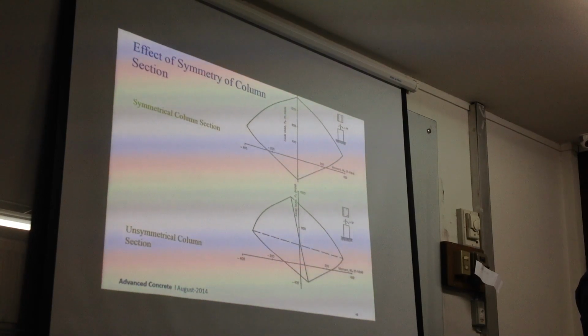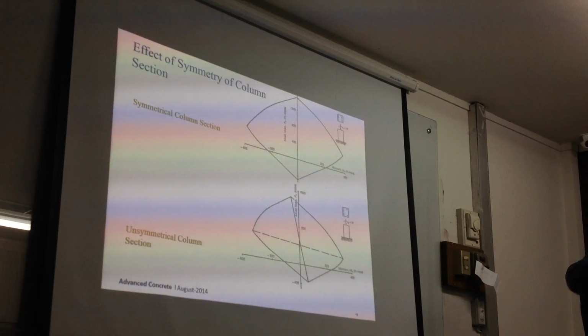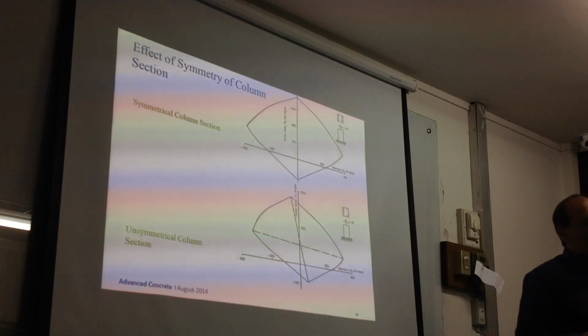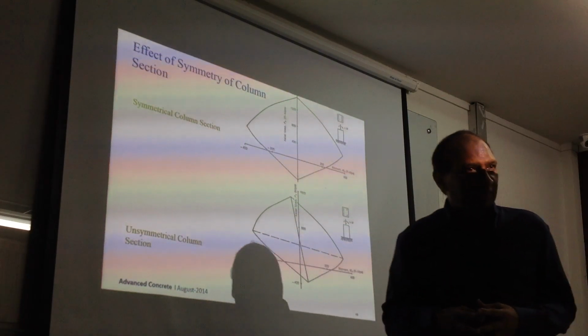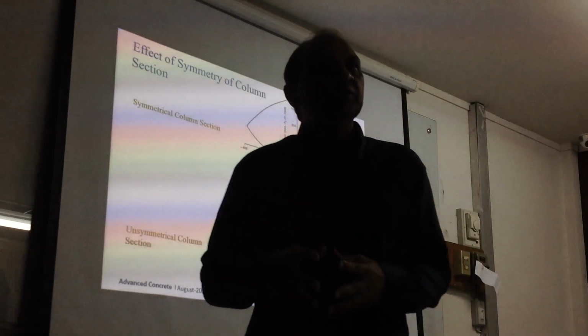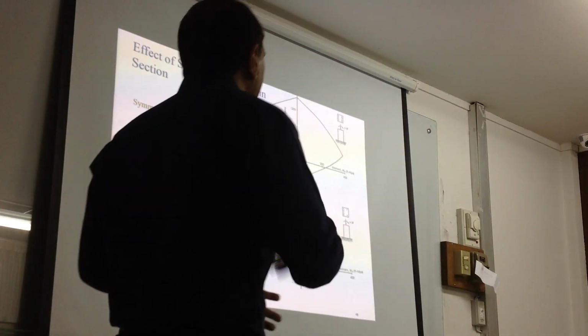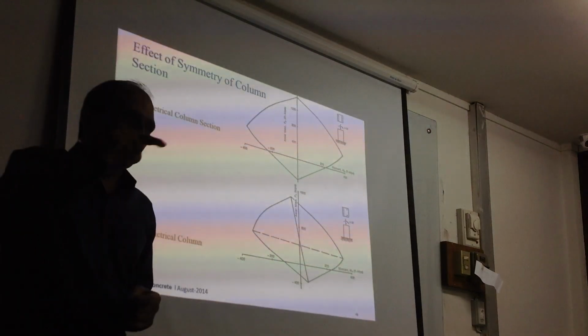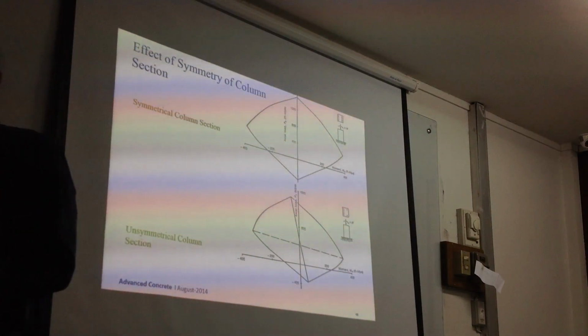As I told you last example of that pile that got cut, I can't do anything. Somebody forgot to put 2 bars in the side. So what do you do? You have now, instead of 16, you have only 14 bars. So you need to calculate what happened now. So that's why the knowledge of the unsymmetrical reinforcement, unsymmetrical sections and everything is very important, especially when we talk about shear walls later, after midterm.